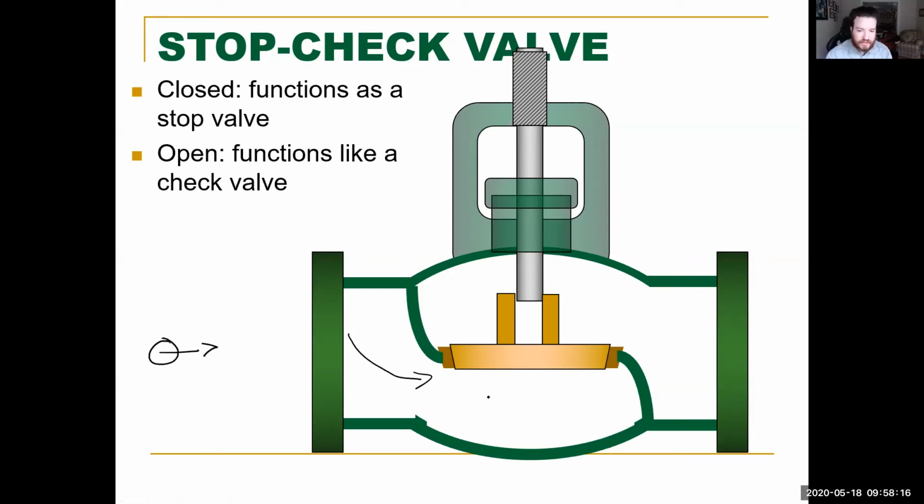As soon as there's pressure, this disc is going to lift up. But now, say you have a fuel pump failure and the pump shuts off. You don't want whatever is in your tank to backflow. So since there's no longer pressure pushing this disc up, it shuts closed, and now all the back pressure is keeping that disc from opening. That's what makes these valves so great.